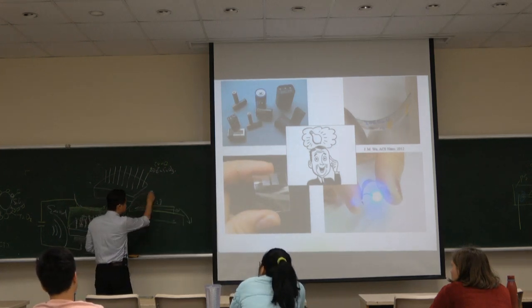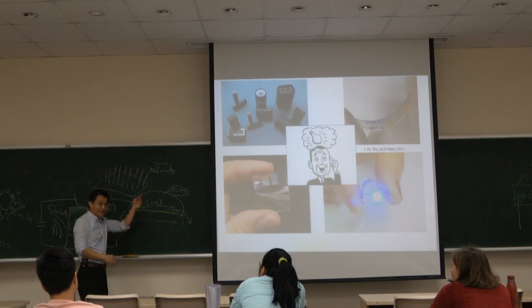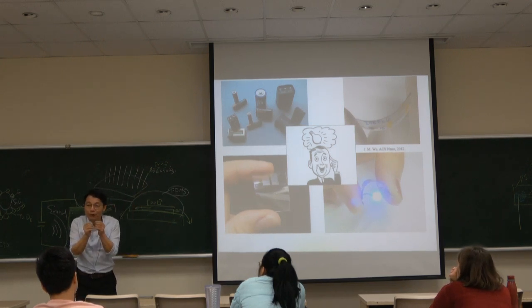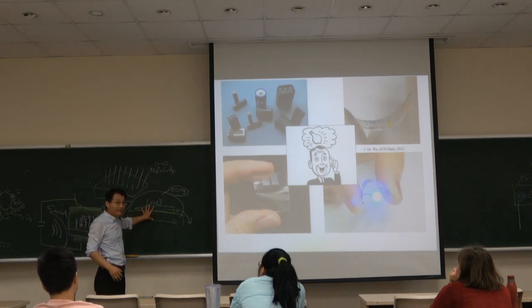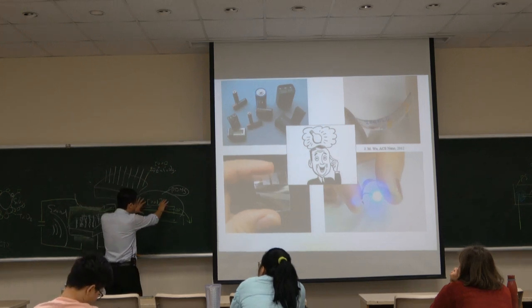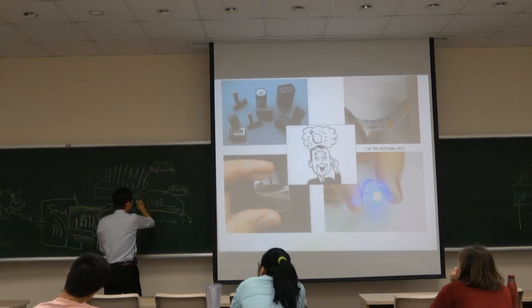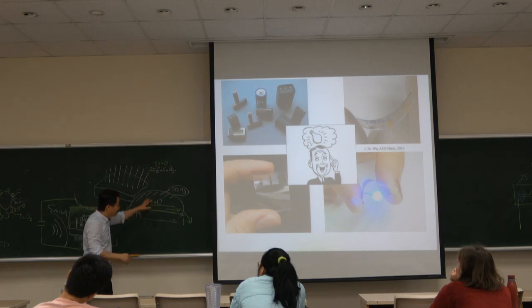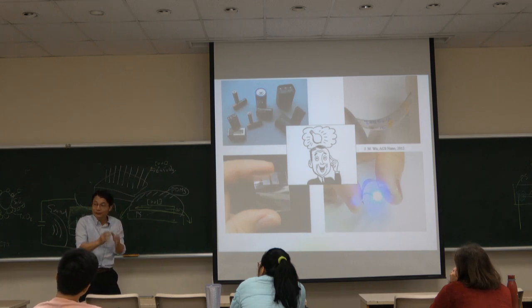I used PDMS to protect. PDMS is one of the polymers that can fix the nanowire, just like a package. So when you bend it, the nanowire will not be damaged. PDMS is soft. And then the PS is right here. Once you drop the PDMS, because it's a solution, you have to bring this device to the oven, anneal, right? And then solidification.